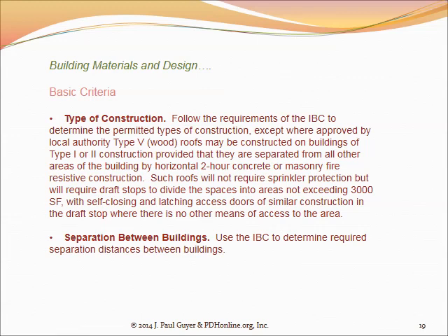And you don't want the fire to break out of the roof, because that's how fires spread from one building to another. Debris blows over, things like that. So the fire-resistive construction of the roof is a very important element in fire protection engineering, as is the separation walls if your building is close to other buildings.